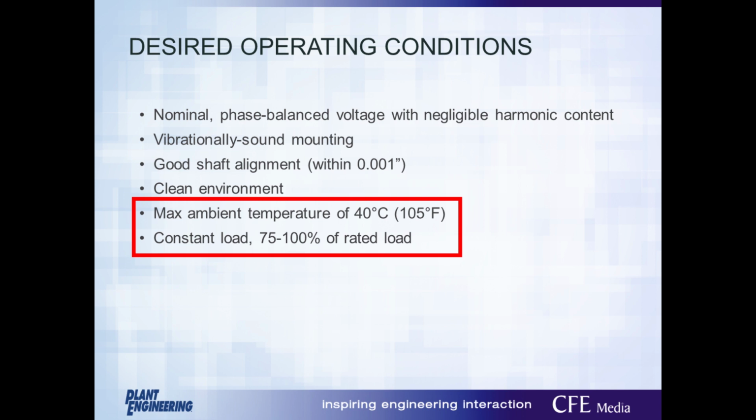Secondly, your motor should be aligned to the load to have as little mechanical vibration as possible. This is achieved typically by good shaft alignment. There are various tools out there, so having a laser alignment tool may be a good addition to your toolbox, especially if you do a lot of motor installs in-house. Otherwise, verify that your service provider is using some type of precision alignment tooling.